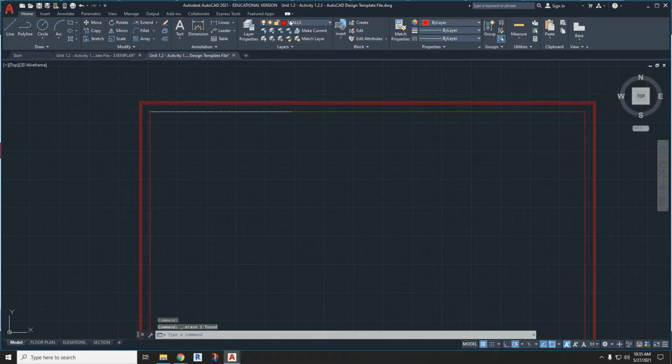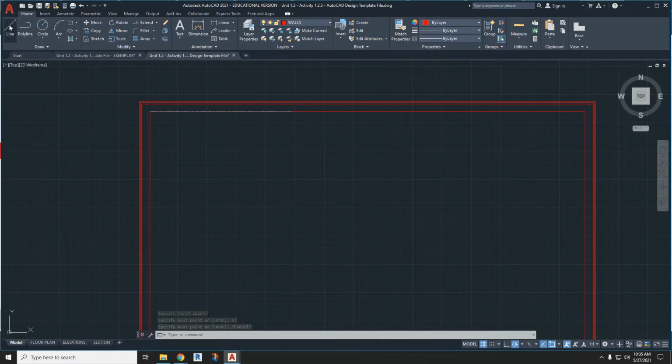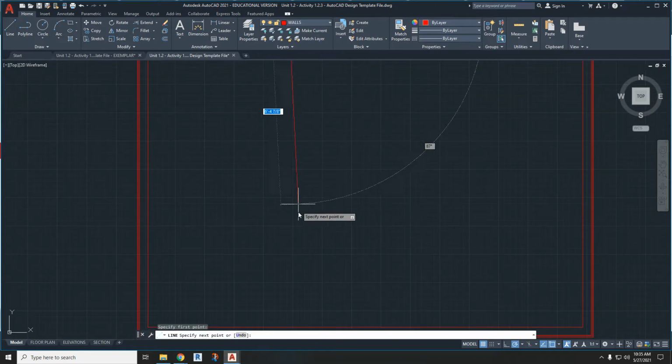So again, when I was trying to draw a construction line and then do that, then call it 5 feet. Okay. And now I can start drawing my walls again. So a wall line here, which is what I was trying to do all along. And then again, do an offset of 3.5 inches.